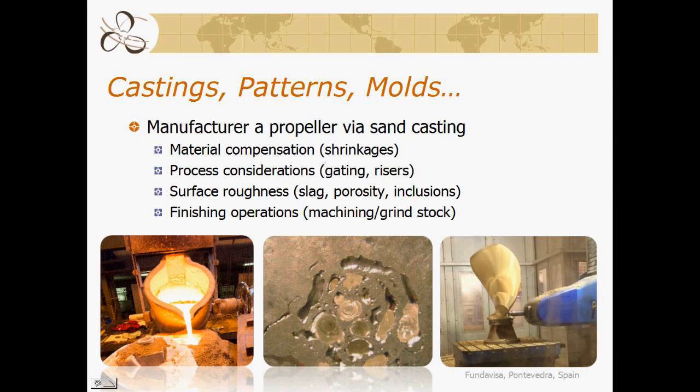For instance, we need to make sure that there's no slag, porosity, or inclusions, such as we see in the middle figure, and we need to be able to remove any of those defects through our finishing operation, whether that's CNC machining, hand finishing, or grinding and polishing.